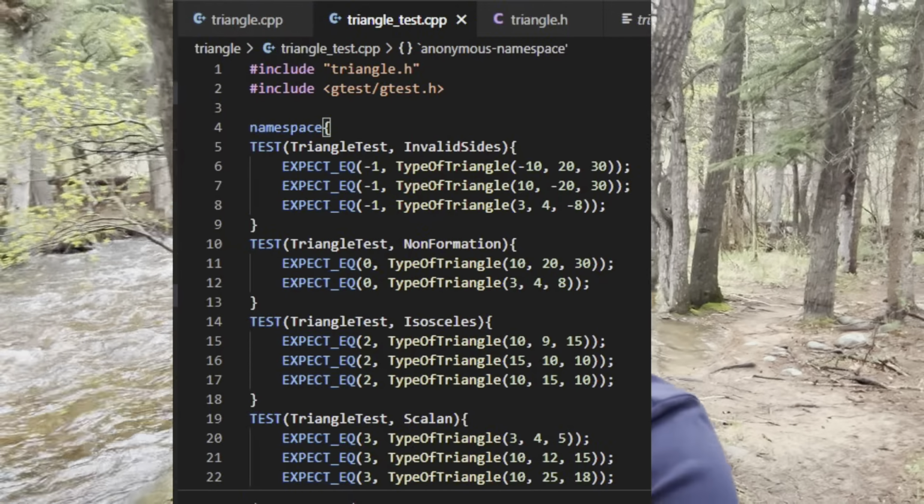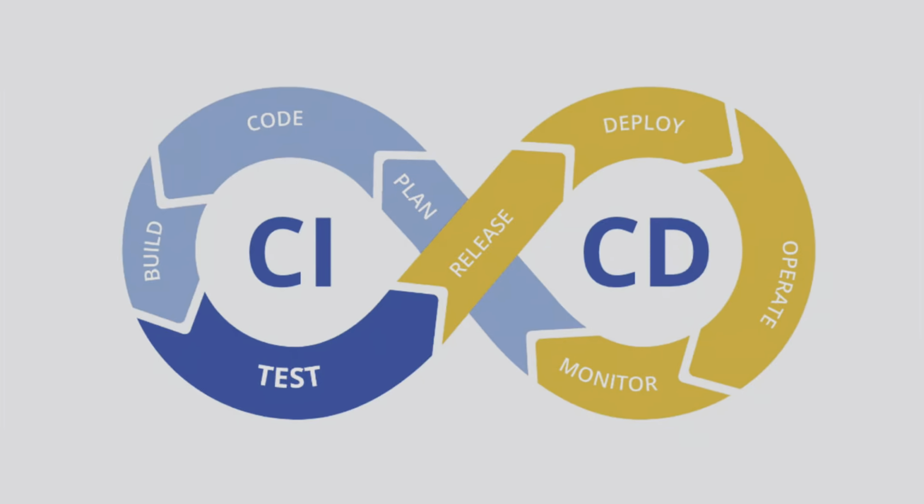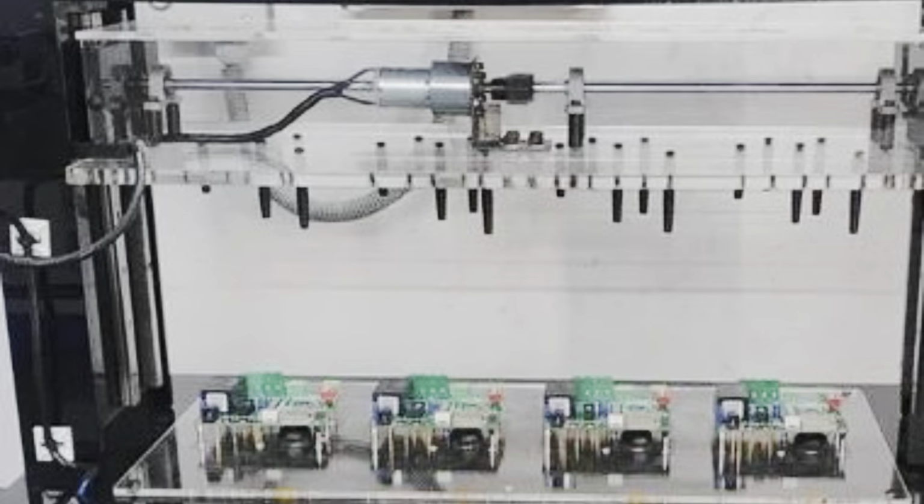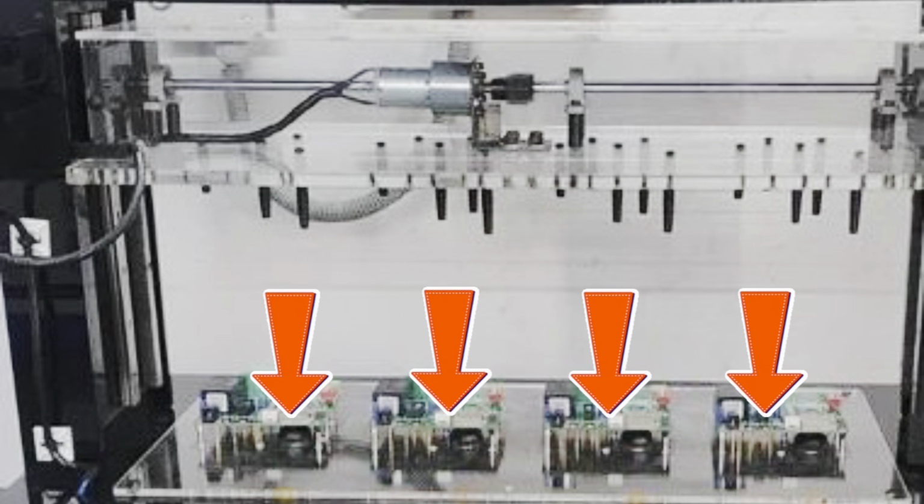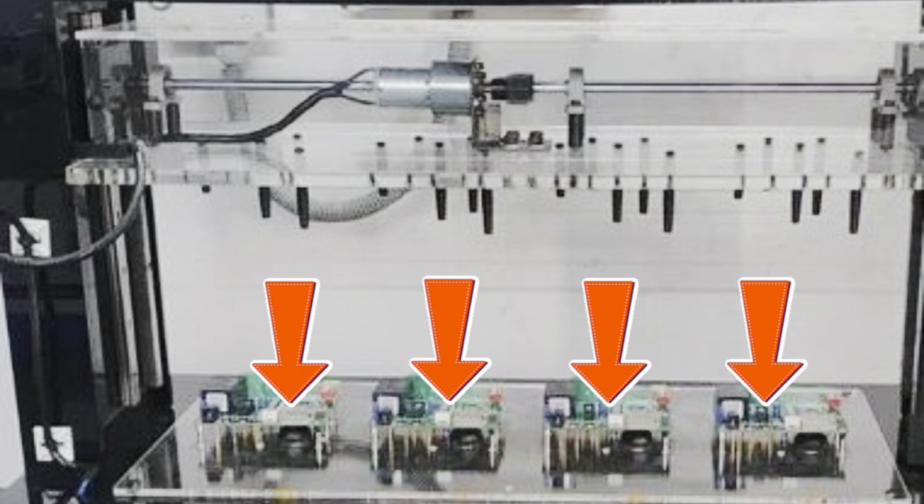Nobody cares about a car like that. So that part is really important. And you can automate those processes if in your software you have unit tests. You have continuous integration, continuous deployment, which makes sure that anytime you make a change in your code, you're able to test all the features. For electrical systems, you have a test jig, which can go in and test all of your points in the circuit by giving them different inputs and make sure that the whole thing works. So before shipping out any product, before shipping out any feature, you have to make sure that everything works throughout.